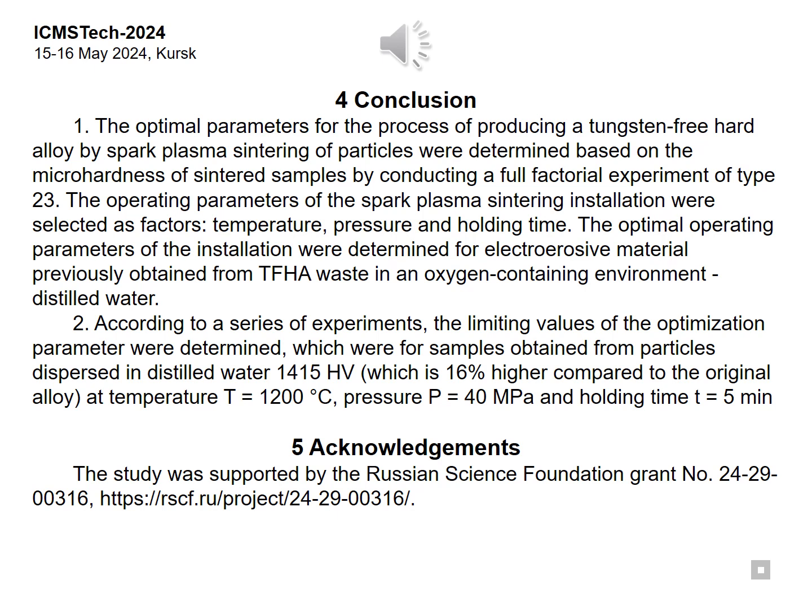Second, according to a series of experiments, the limiting values of the optimization parameter were determined, which were for samples obtained from particles dispersed in distilled water 14-15 HV, which is 16% higher compared to the original alloy, at temperature 1200 degrees Celsius, pressure 40 MPa, and holding time 5 minutes.